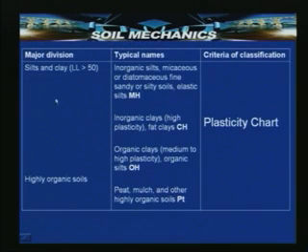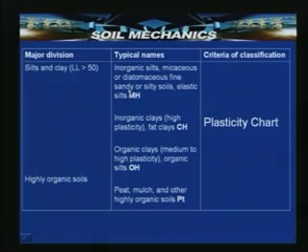The next major division is silt and clay with liquid limit greater than 50. Previously, we have seen the fine grained soil with the liquid limit less than 50. Now, we will be seeing the silt and clay with the liquid limit greater than 50. Inorganic silts, micaceous or diatomaceous fine sandy silty soils, elastic silts, are MH.